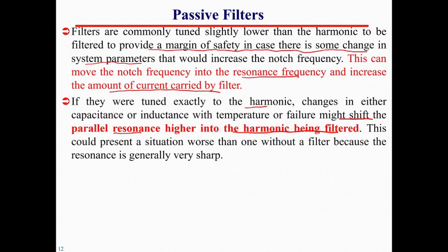That's why we have to make our design such that it will not be equal to the resonance frequency. It is a little bit lower than that. This could present a situation worse than one without a filter, because the resonance will be very sharp, and definitely that will cause voltage and current to shoot up to very high values.